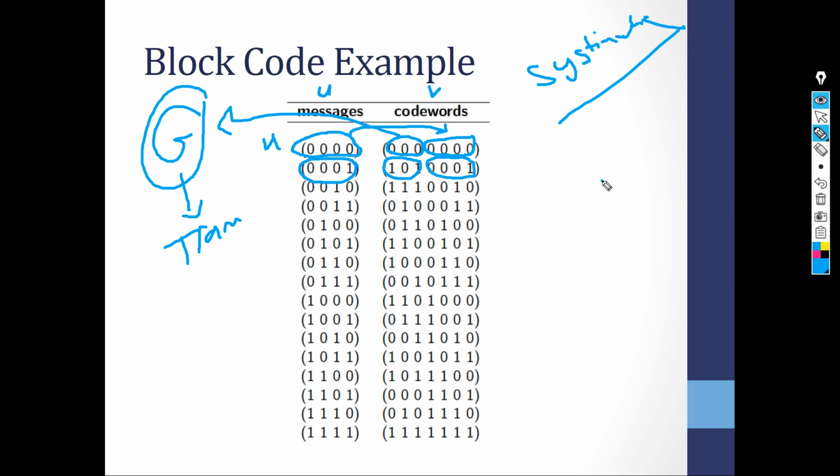Let's say you have four basis functions, like this. And you have the length of these basis functions, and you have your message vector here. Your message gets multiplied by the vector and the result is 1 bit. By the next, and the result is 1 bit. These bits, you put them at the end of the message. We will talk about them in detail, but for now, let's just understand that the systematic encoder puts the message bits themselves in the code word.